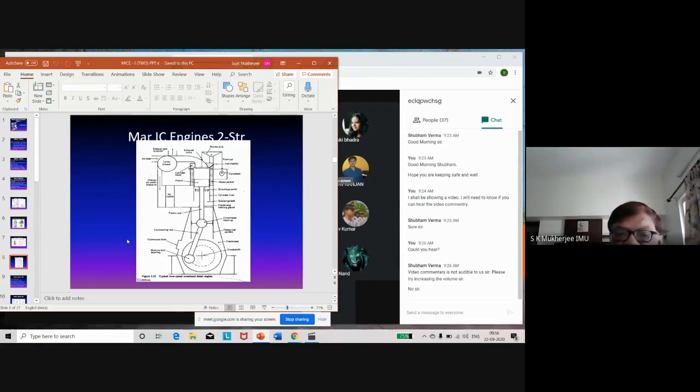Second one is the speed. The shaft must have a particular speed to enable that oil to go underside of the shaft. And that speed should not be too slow. If it is too slow, by the time the oil is dragged, it will get pushed out. So the time is a factor. So that means speed makes the difference. So you have viscosity and you have time. Third factor is the clearance. How much clearance is provided for that bearing will enable the shaft to rise and allow that oil to come underside of that shaft. If there is no clearance, then the shaft cannot rise and the film of oil cannot form. So that is the third one. The clearance has to be satisfactory.